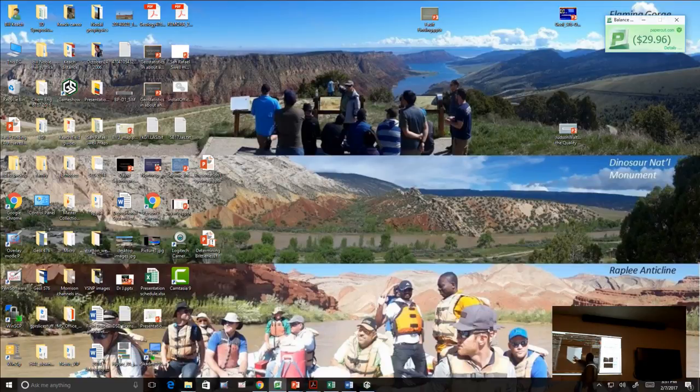I've got 4 minutes left. One last thing before we get out of here. If you want to animate through the data, make sure you're in arrow mode. Put your cursor on the face that you want to animate. Hold down your shift key and the left mouse button and it will drag around.